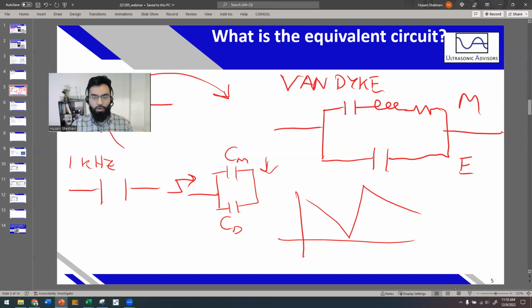There's another type of circuit which can focus on the anti-resonance, but also includes resonance, because to have this circuit work for a large frequency range, you need to encompass a lot of other features. For example, at off resonance, at low frequency, this circuit simply becomes two capacitors.